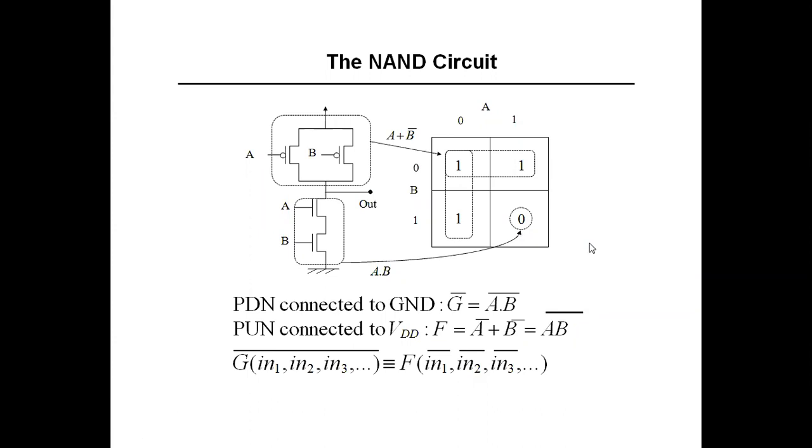So how are we actually implementing it using CMOS? As you know, when you talk about CMOS, it's a kind of pull up network and pull down network. The pull up network has to be of PMOS, and the pull down part has to be of NMOS. So this is A bar plus B bar, if you analyze it using the K-map equations. The pull up network has to be connected in a parallel fashion, and exactly reverse of that is the series fashion. Why series?